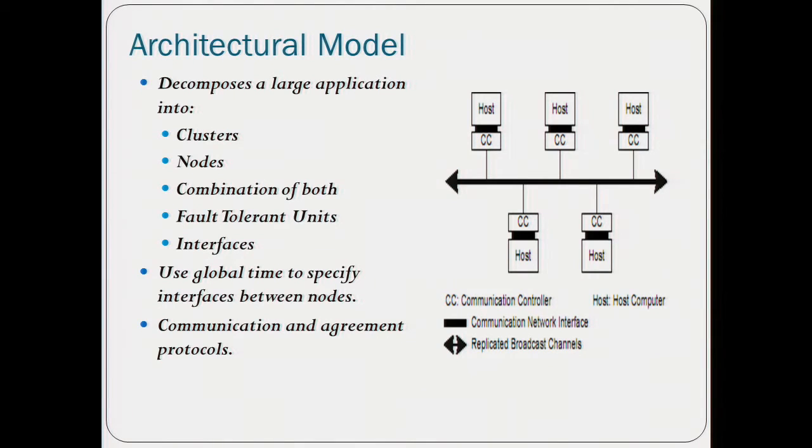And then the CC is a communication controller that takes the data from the computation and sends them on the bus. So it controls the access to the communication network, right? And so we saw already that one way of doing it is to split it in two, having a buffer where you write and a buffer where you read. Okay.